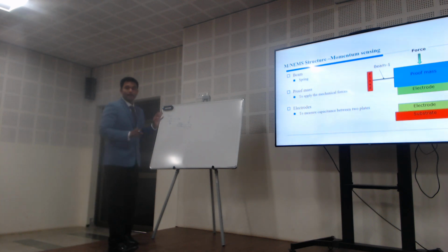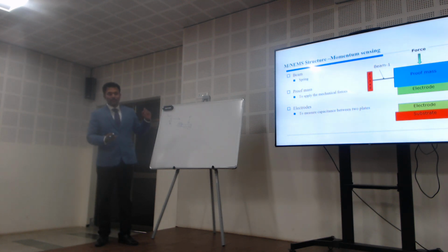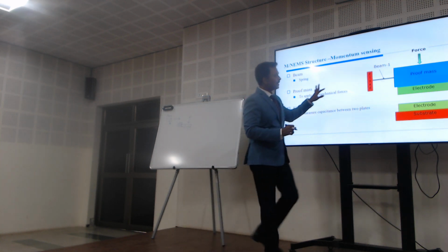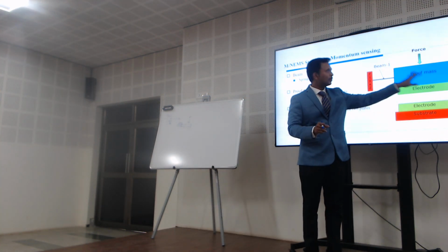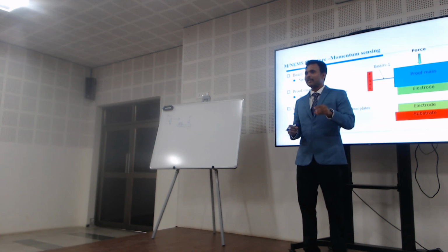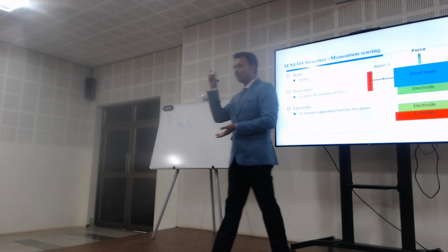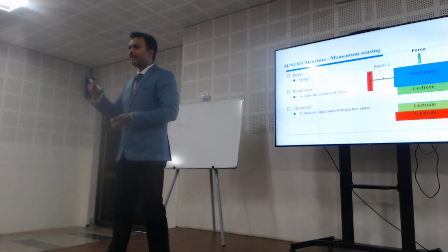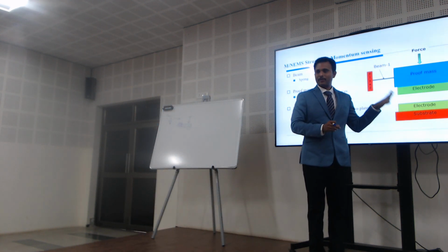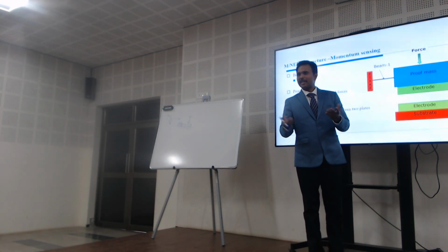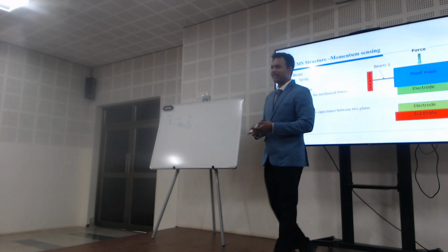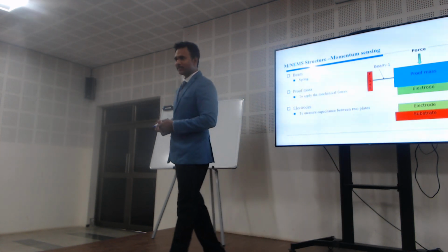Whenever it changes its position, I keep two suspension beams attached to one proof mass. The proof mass is where we apply the load, where we apply the force. And here I keep two electrodes. That is our basic principle: two electrodes in parallel with a medium, and the capacitance changes.